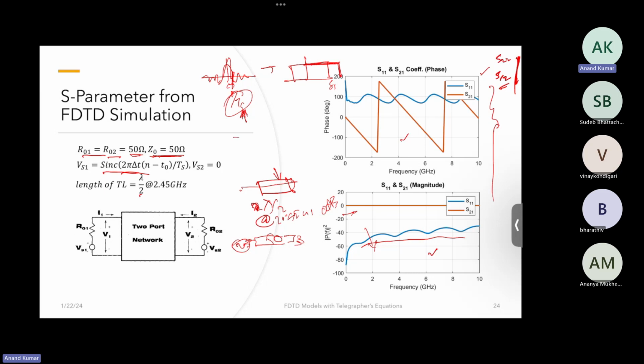So the idea is that this particular rectangular pulse means you're giving a particular power in at each frequency. If I choose this to be 10 gigahertz, for example, then up to 10 gigahertz this is a rectangular pulse, meaning each frequency, for 1 gigahertz, 2 gigahertz, at each frequency is getting a power of, for example, 0 dBm.